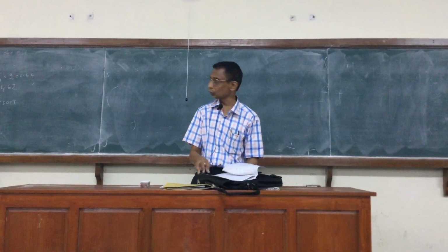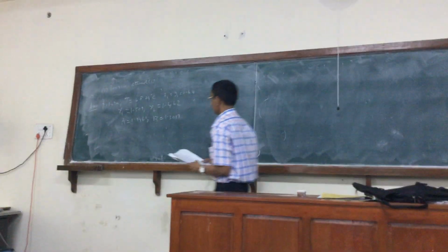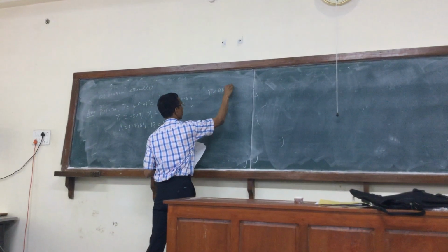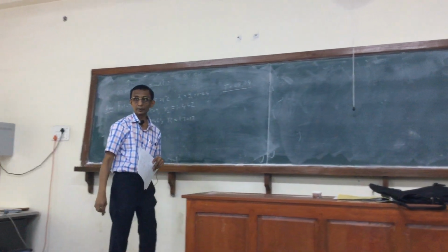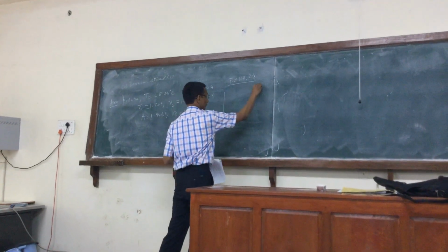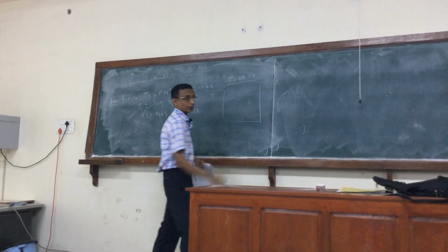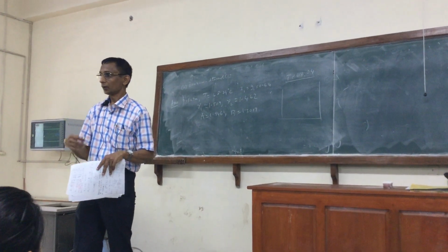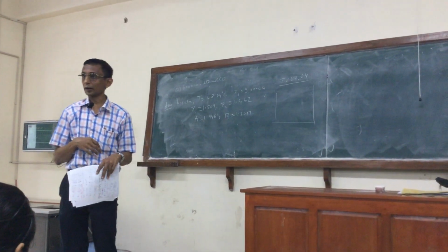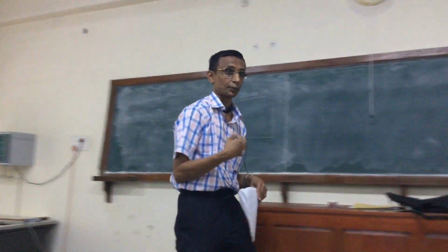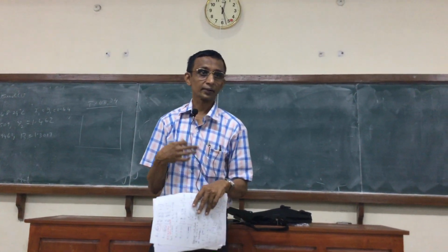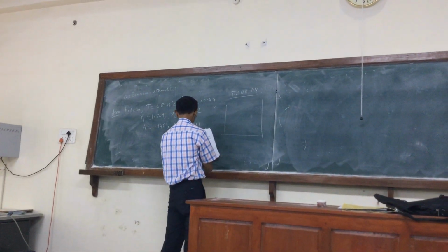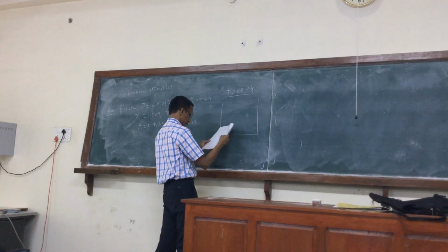So with this, we can now move directly to construct the diagram. So if I take T equal to 68.24, how do the rest of the points look? We can easily verify, because here we can calculate the bubble pressure, which is very easy to do. We want the Pxy curve at T equals 68.24, to actually check whether this would have a maximum at the azeotrope. If you want to check that, it's very easy to do by simply looking at the endpoints, which can be easily calculated from the Antoine equation.